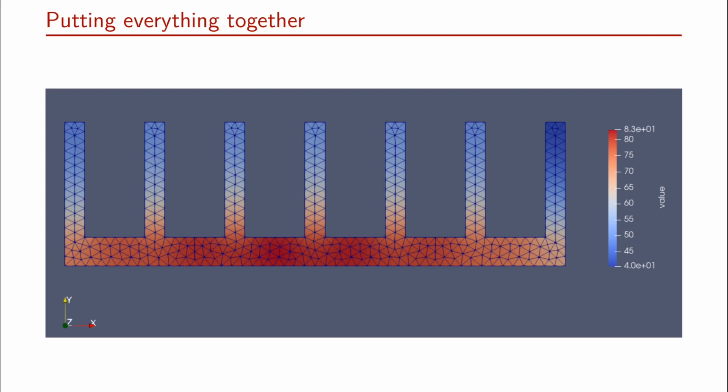Now, if you put everything together, basically this was adding the source term to our numerical simulation, which first of all simulates the creation of heat down there, then adding the part of the Robin boundary conditions to the source term, which does not depend on the solution, and then the third step is that we modify the matrix according to the part of the Robin boundary conditions that actually depend on the solution. So if we do these three steps, and modify our code appropriately, and run a simulation like this, then we should get a result like that.